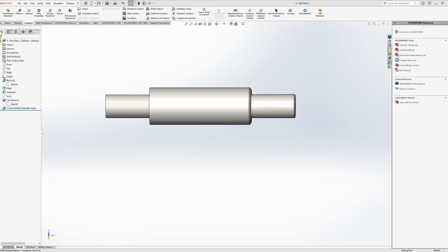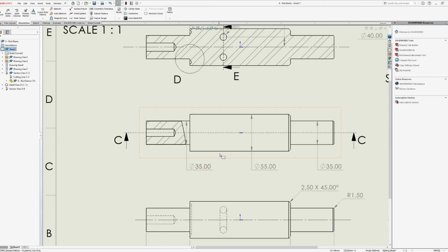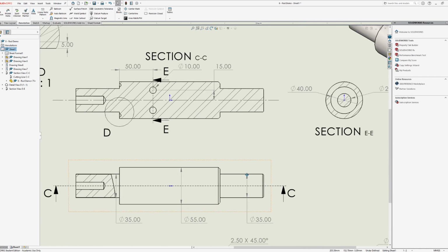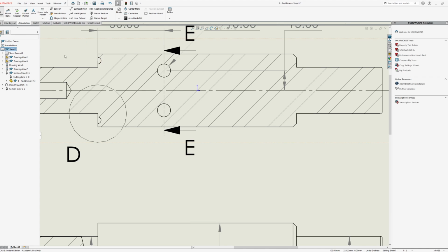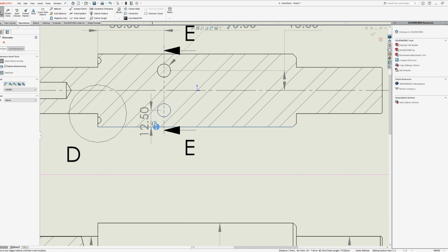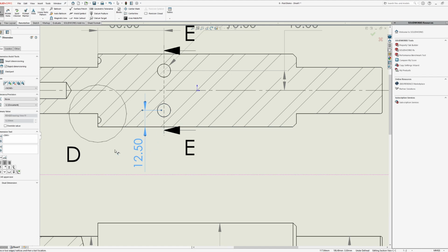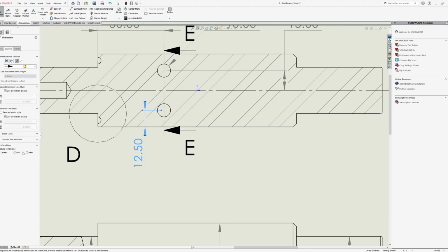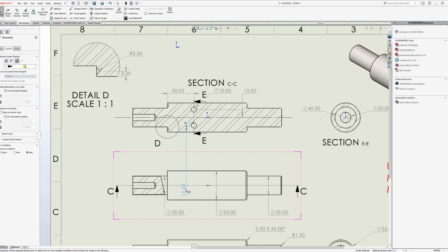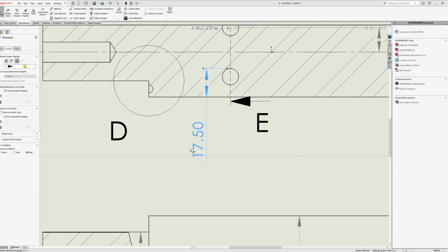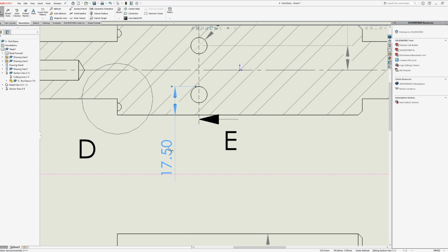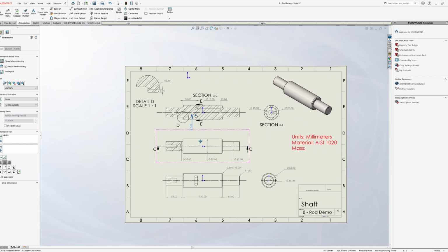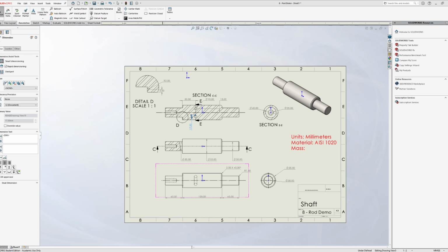So remember how if I go back over here to where we have something that is kind of like an arc surface, say I'm trying to dimension this circular cutout, I can go into leaders and I can dimension it either from the center, which is default, but I can also dimension it from the minimum value, which is literally just from the edge to the closest point on the circle, or the furthest point on the circle. So those are little details that you should also just be mindful of when we're looking at certain diagrams and playing around with them, making drawings for them and some such.